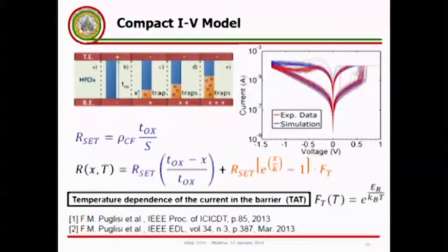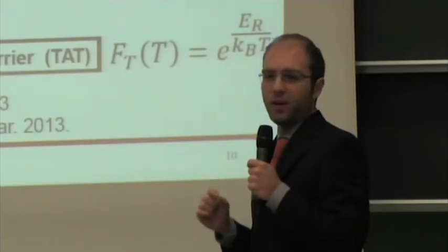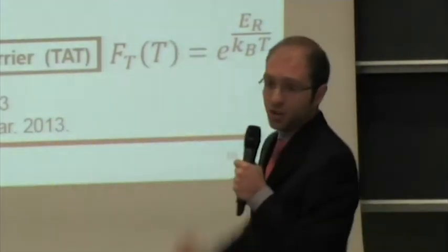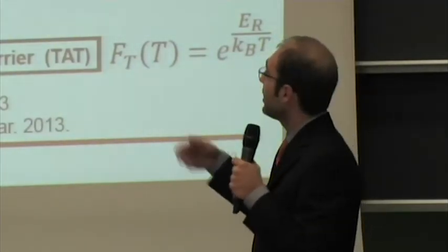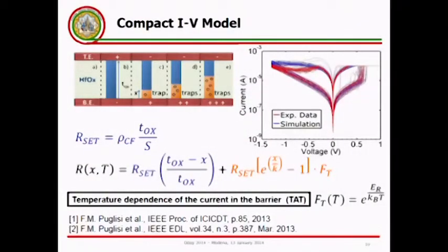So through simple IV measurement we can estimate at each switching cycle in low resistive state the cross-section of the conductive filament. On the other hand, when we apply a negative voltage ramp, the bottom end of the conductive filament gets dissolved, and a dielectric yet defect-rich barrier is formed in its place, which is the orange part, and its thickness is related to the reset condition. So the higher the reset voltage, the thicker the barrier, the higher the resistance in high resistive state.